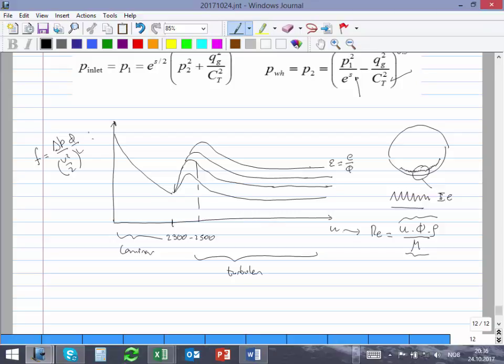And then what you do is just adimensionalize. Adimensionalization is a very powerful weapon. When I did that, I basically made a general plot that I measure only once and then everyone can use. You don't have to repeat measurements. Also for the deviation, please keep that in mind. That's what we did. We adimensionalize pressure drop, adimensionalize velocity, and then we have a generic plot.